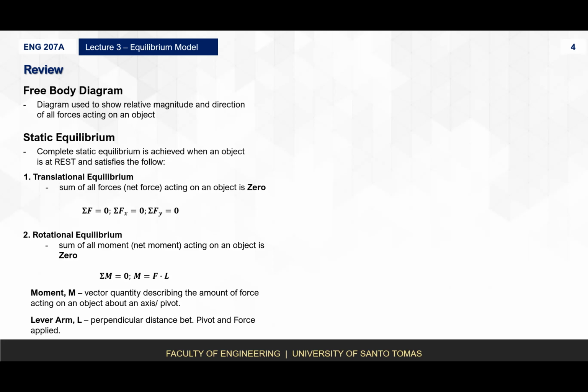To get the moment, you simply multiply your force by the perpendicular distance. If your force is applied directly at the center of gravity, your moment will be zero because you have no lever, you have no distance to leverage to multiply the force. Okay.